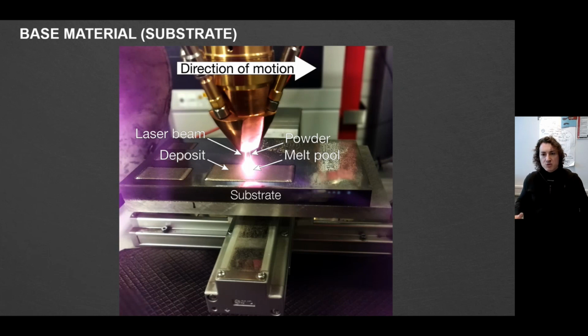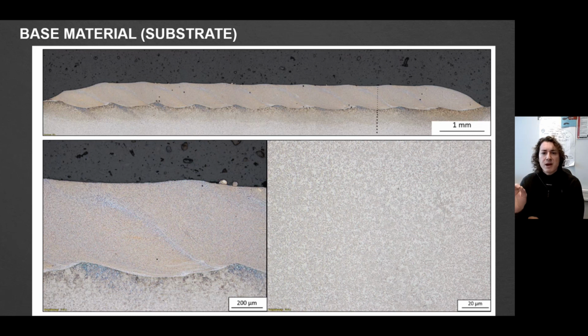And there are a couple of general rules which can help you to find the right approach, how to interact with the substrate and how to make your laser cladding process successful. The interaction with the substrate does influence two things. First of all, the properties of your coating, due to dilution and of course diffusion of substrate material into the coating and vice versa. And from the other side, it does influence the properties of your substrate. You can get a heat affected zone, you can get cracks, and all those phenomena have to be studied.